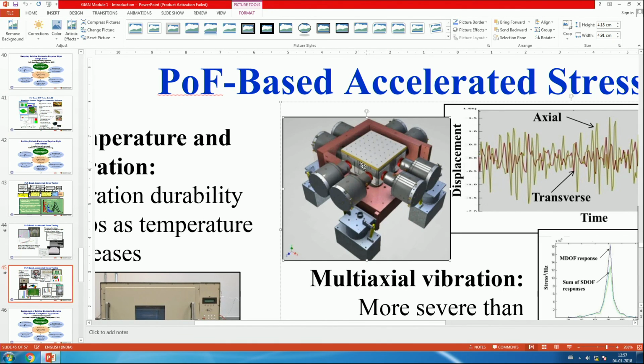And then you can see 4 actuators on the x-axis, 4 actuators on the y-axis, and underneath, you cannot see it, there are 4 actuators in the z-axis, the vertical out of plane. And by firing these in the right sequence, you can produce vibration in x direction or y direction or z direction or combinations of those. Or you can do rotations.